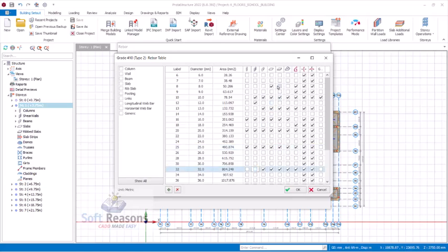All right, so for the beams, we are not going to use 10, we're not going to use 30. We use 16, 20, and then 25 as the highest bar diameters. For the links, we are going to be considering 10 and 12. The program is going to choose 10 for the links successfully.